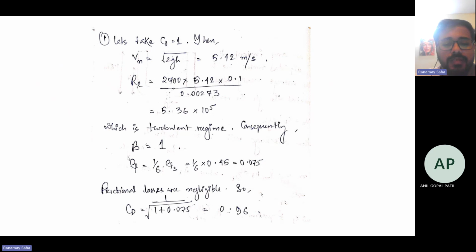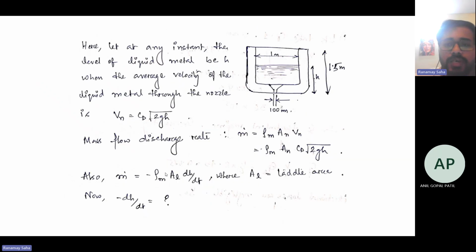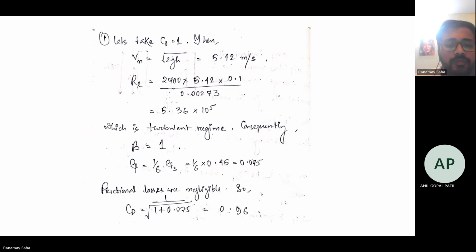And then there is one coefficient, EF, which influences the friction factor F. EF varies for different kinds of geometries or inlet areas. In the case of a tapered geometry, and we have a tapered geometry here, right, tapering out toward the outlet, EF gets modified as 1/6 actually.